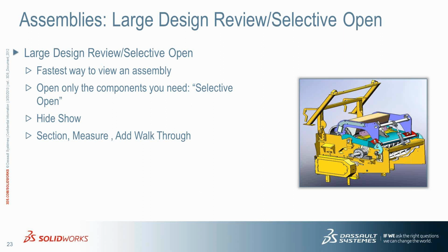Now from there, you can open only the components you need to work on, what we call selective open. You can also hide and show components. You can section, measure, add walkthroughs, take snapshots. There's a lot of things you can still do by entering into this mode, and I wanted to show you a little bit of that.